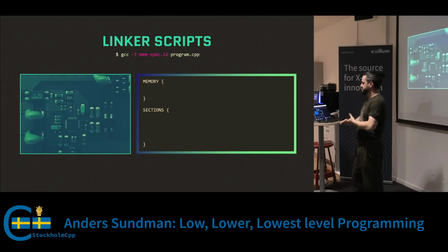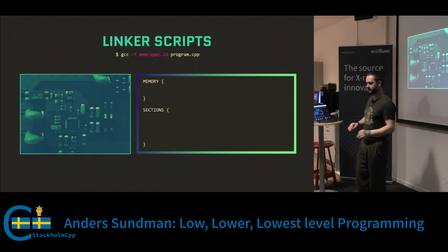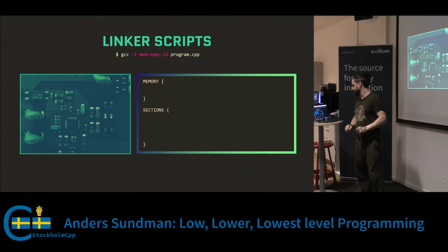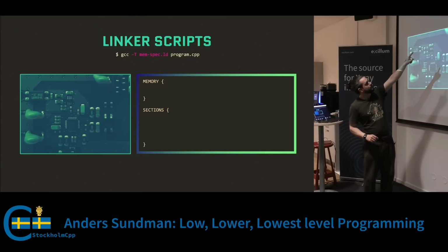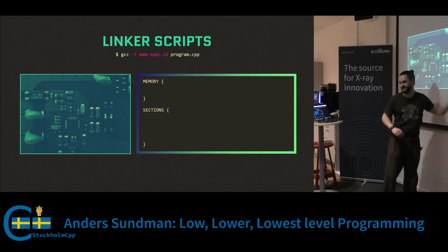And linker scripts are one of these a little bit mythical things, like it's rumored that someone knew how to write linker scripts sometime, but it's actually not complicated. So I'll just go through it. You specify a linker script with -T, and then you specify a file name. And the file looks basically like this. It has two major sections, MEMORY and SECTIONS.